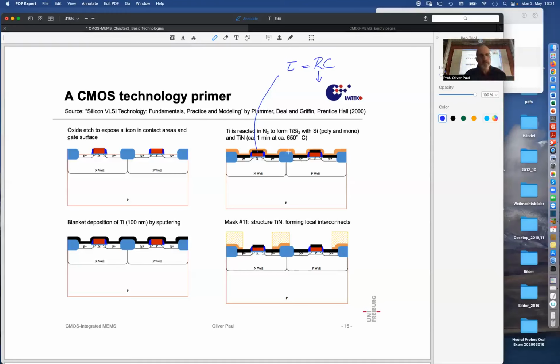So in this particular technology, the contact to the source and drain is now directed over the field oxide, kind of into the safe region. You have these delicate structures. If you can avoid some later harsh processes like drilling holes into some insulator, those technologies have avoided that by moving that aside.